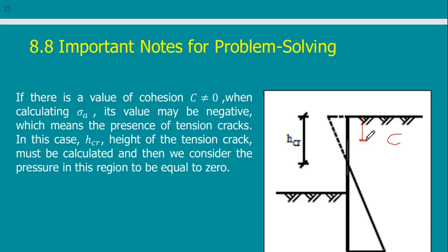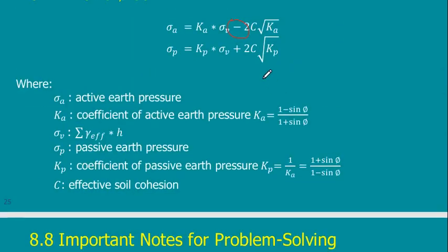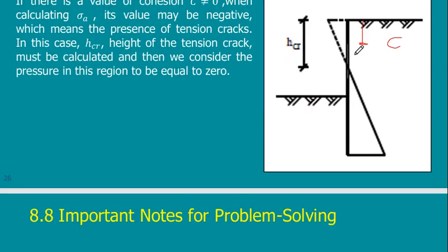This increase starts adding a contribution of the phi in my equation, so this term starts to increase till I reach a location where this term equals this term. This will be the location where I have 0 pressure. Once I have 0 pressure, I start to have a positive pressure on the wall.